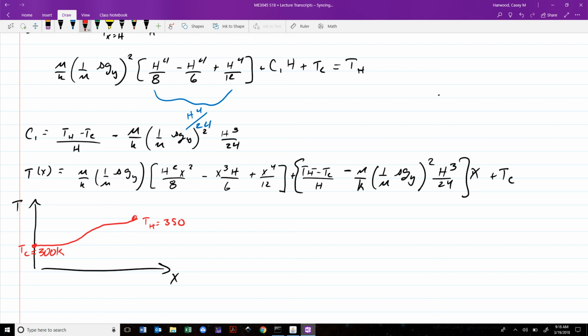And you remember the reasons we get these sort of nonlinearities, right? They come from all of these terms that have 1 over mu rho times g squared. Rho times g squared, yes. That first term right there. And the reason we get these nonlinearities is they're all tied to these parts that have mu in them, right, viscosity. So these come from the tendency of the fluid to generate frictional heat due to viscous dissipation, right?